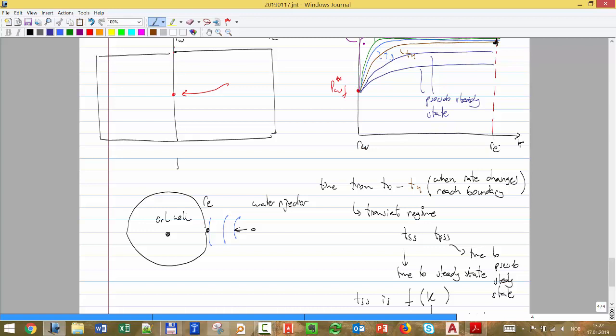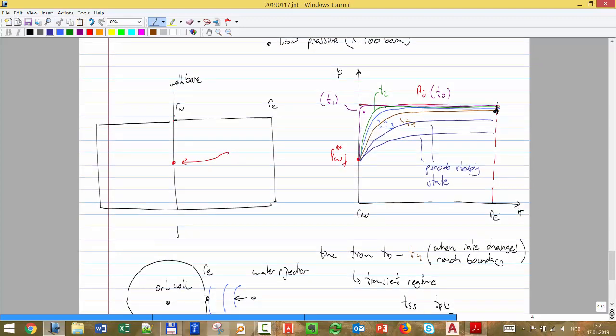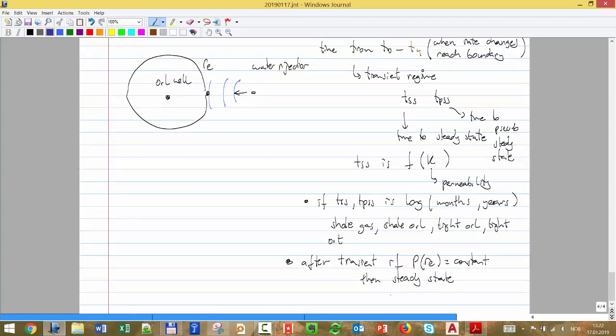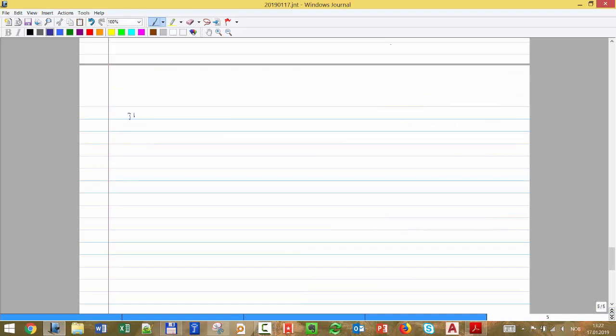Now, one more step. If you are in the steady state or pseudo-steady state, you can remove time from the whole equation. If we are in the transient, we have to track this interface, and what happens with the perturbations in pressure is messy. But in the pseudo-steady state or steady-state regime, we can take time out of the picture. So in steady state or pseudo-steady state, the rate of the well can simply be a function of P_R and P_wf. We don't need to include time.